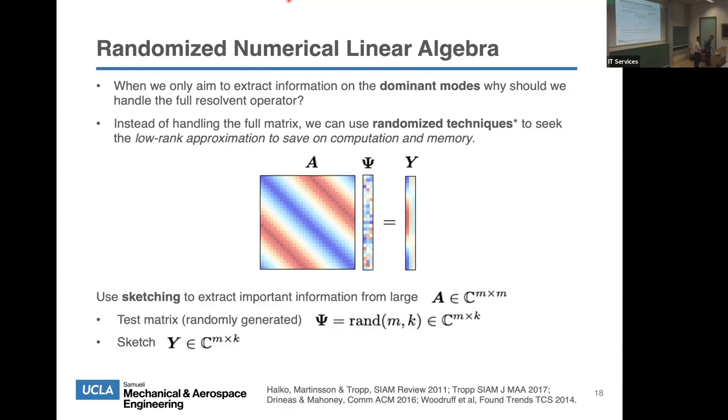So I wonder, this is an inspiring approach. I wonder how far you can go with this resolvent analysis, and give you a couple of ideas. If you have the airfoil and you have a gurney flap, then you can do a very nice lift increase and separation control, but the gurney flap essentially cannot be in your original data. Another thing is maybe you have to do high frequency forcing, something like a turbulator, to change the structure of your boundary layer in order to achieve your separation delay.